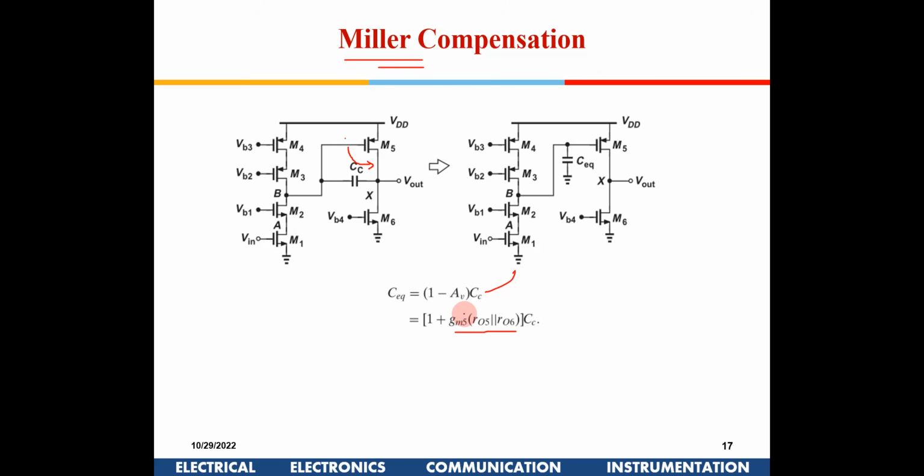Why have we done this? We can use a smaller capacitance and achieve a dominant pole here. Smaller capacitance means the value of the capacitance will be small, and hence the area occupied by it will be small. Yes, but if we put less value, then the gain does not come out good. This capacitance is not making any difference.